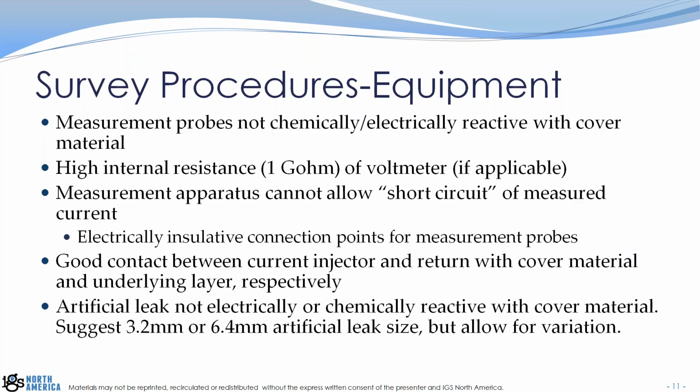I always thought this was pretty much obvious as far as equipment goes, but a lot of the equipment out there is homemade, and people don't fully understand that all measurement apparatuses are not the same. I've had a well-made dipole sitting side by side with a very poorly made dipole. The well-made one measured 10 times more voltage because the poorly made one was not electrically isolative, so it was getting short-circuiting through the legs. So if most of the current is traveling through the legs, you can't get a real precise measurement of voltage right at the points where you're trying to inspect.